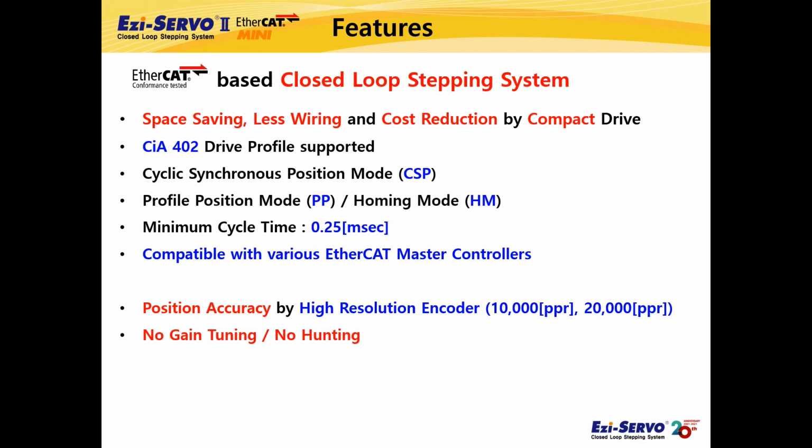For example, you can just power on the motor and operate it without gain tuning. Since the holding torque is large, there is no vibration after stopping compared to the servo. In general, when controlling a stepping motor, motor heat is a problem because the maximum current flows regardless of the load, but since Ezi-SERVO controls the current according to the load like a servo, it can relatively suppress heat generation compared to the conventional stepping motors.